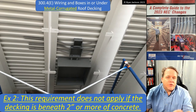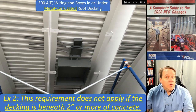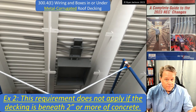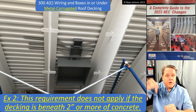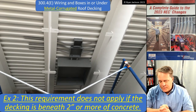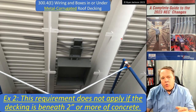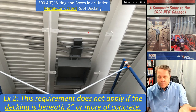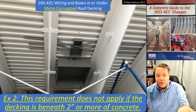Now, the second exception was added for the 2023, and I'm really happy to see this. It says, look, this requirement does not apply if the decking is beneath 2 inches or more of concrete. The informational note said this rule is there to make sure that roofing screws don't hit your raceways or your cables. So what if I don't have a roof above the metal corrugated sheet roof decking? Because the metal corrugated roof decking, that's not saying necessarily that it's on a roof. That's just what the product is called.